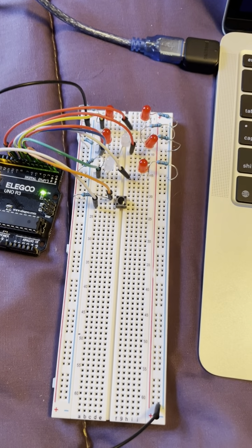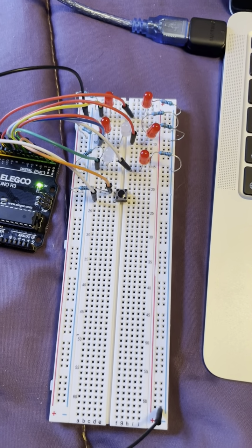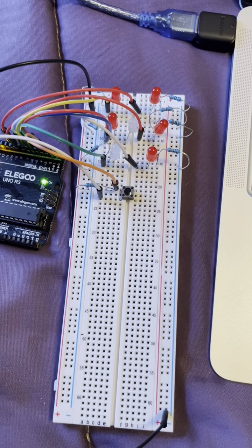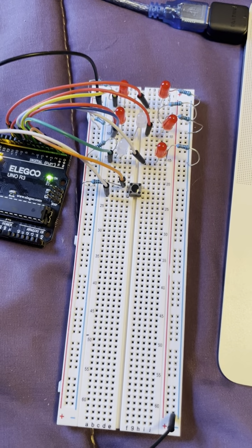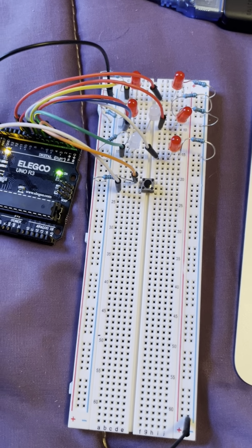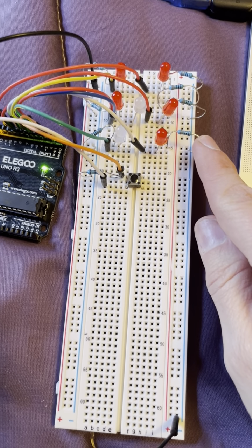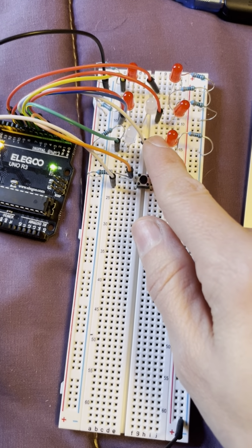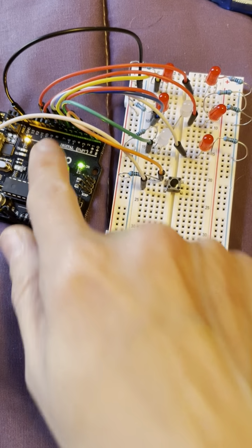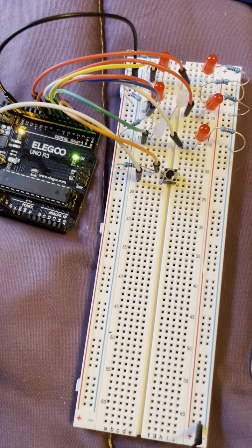The circuit includes 7 different LEDs that are set up in an H pattern so that I could generate each of the number patterns that show up on a 6-sided dice. Each LED has a 330 ohm resistor and a jumper wire that connects it to a specific digital pin on the Arduino. So in this case, I used pins 3 through 9.